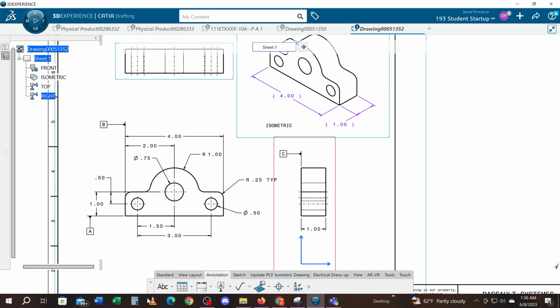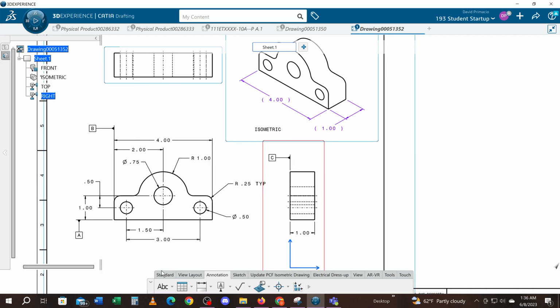And then if I look at this, this is the bottom. This line also is the bottom. This is the front face. According to chapter 5, third angle projection, this front face here, when I flip it 90 degrees, the front face would land here. This would be the back of the part. The back of the part on this is behind there. I can't see it, but up here, this is the front surface, and then this is the back of the part. We're looking at a top view. Flip that 90 degrees. This is the front face and the back view.